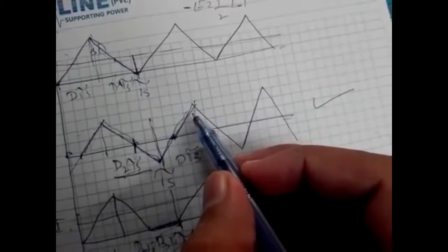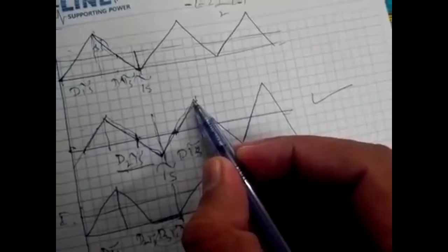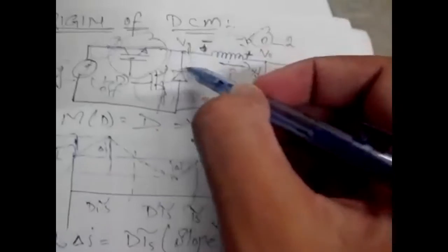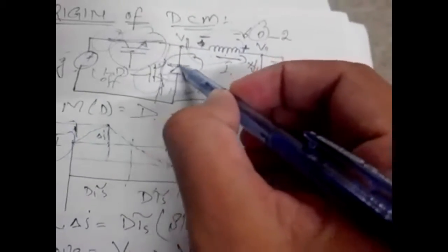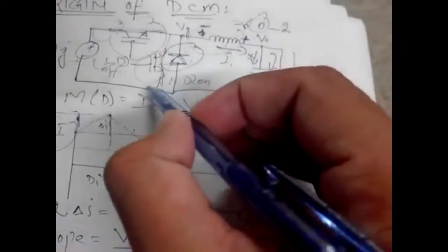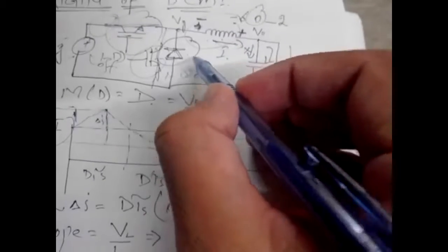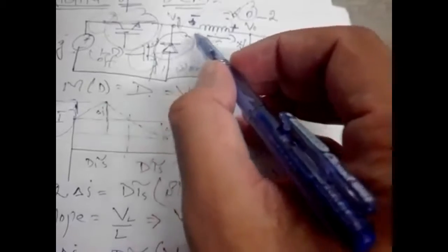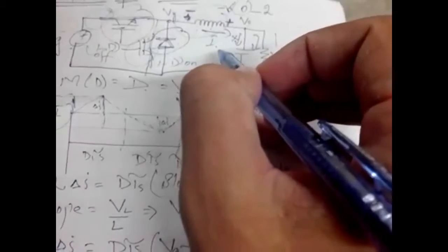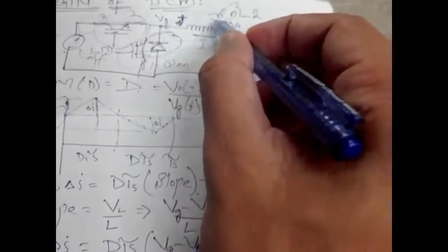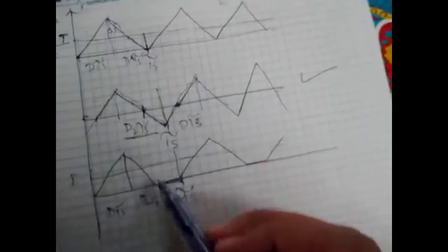So a similar situation also occurs after that when it becomes de-energized. So that's why we connect the unidirectional switch here, which is the diode. In 1 minus D Ts it becomes on and de-energizes into the resistor load, but after de-energization it doesn't allow the current in the opposite direction, so it doesn't charge in the opposite polarity and the current becomes 0 in this diode. So that's why the current becomes 0 in this one, and this is the DCM.